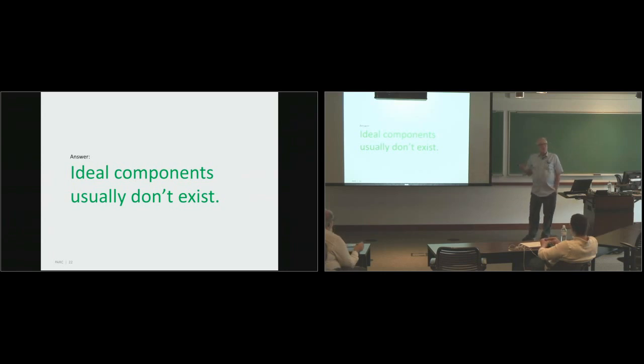And the same thing is for cars or engines. Why does a car have a transmission? A car has a transmission because the torque speed curve for an engine is not linear at all. It's very nonlinear, and your transmission is always trying to allow you to match the speed of the engine to the speed of the road, and then you get more efficiency. But again, it's because there's no ideal engine.